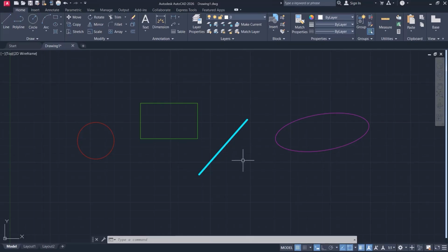Because when we're drawing, the line thickness might mislead us, or when we're working with snaps, if thinner lines intersect with thicker ones, it could confuse us. Basically, line weight or line thickness is important for printing, but it doesn't really matter much while we're drafting. So, usually we do our drawings with line weight turned off. Then, when it's time to print, we turn on the line thickness.